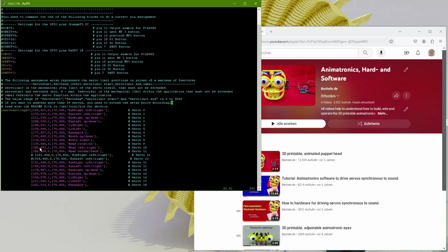Even if you have a new servo or a different type of servo, for example you want to exchange one because it is broken, then by just setting these values again you can reuse your old movement files, because internally the movement files use a virtual movement of 0 to 4096, independent of what the servo in reality does. As I said, this makes it much easier to change servos afterwards, or if something breaks, so you don't need to teach everything again. That helps you a lot.